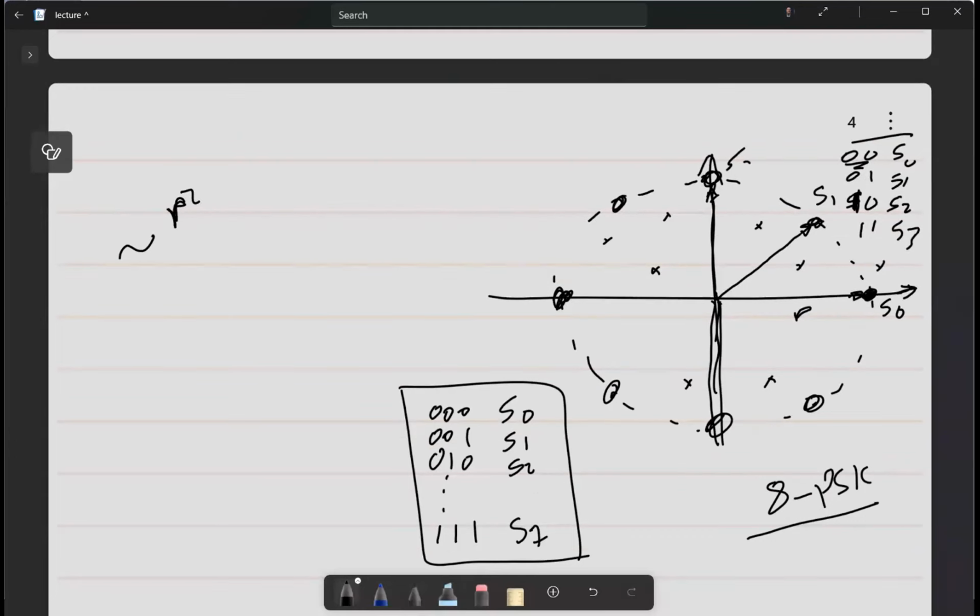So in practice, you transmit your signal x of t equal to cosine 2 pi f0 t plus your transmitted phase, which could be some factor alpha times pi times the symbol I. So here the symbol I is changing only the phase, and you can select alpha and the values of I in order to specify the phases.